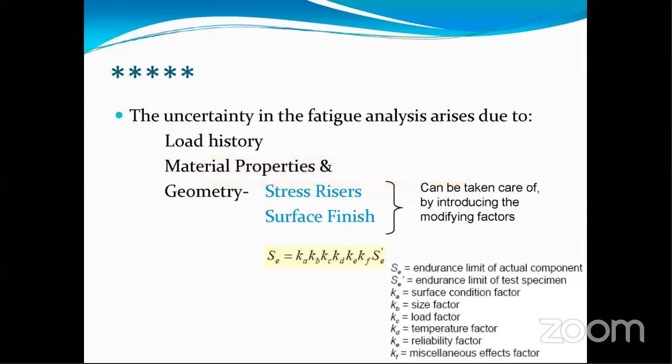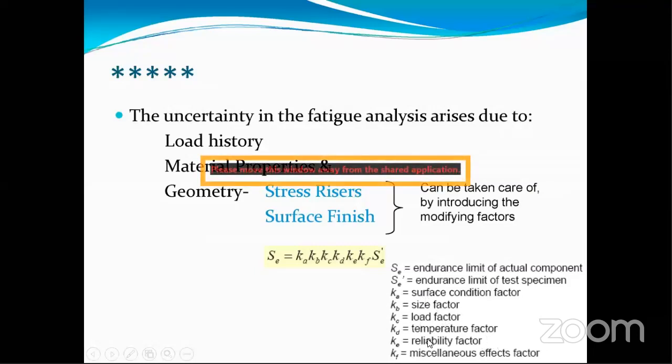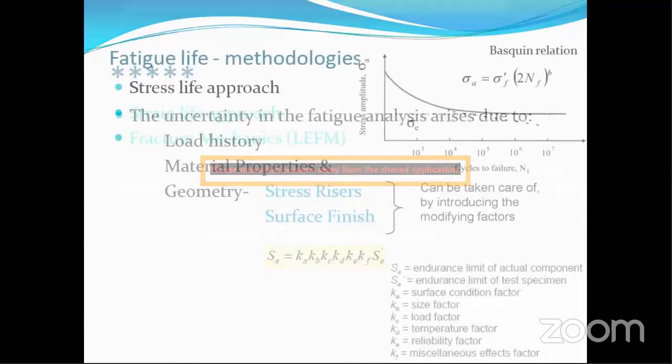Also, there will always be certain factors like stress risers, surface condition, size factor, load factor, temperature factor, and reliability factor. Some other miscellaneous effects also. So these modifying factors are to be assessed from lab tests or actual prototype specimens. Only then will we be able to confidently give the fatigue life of any component.